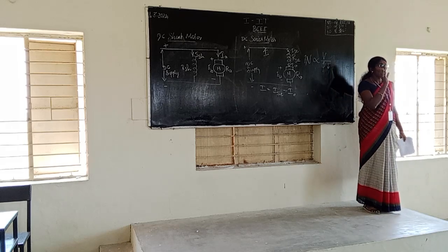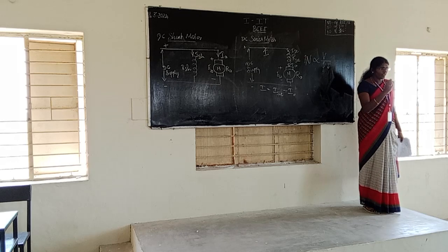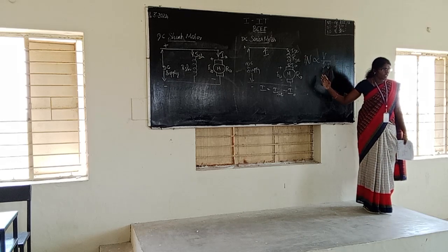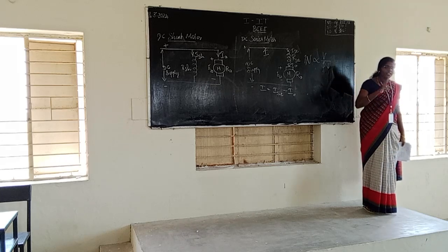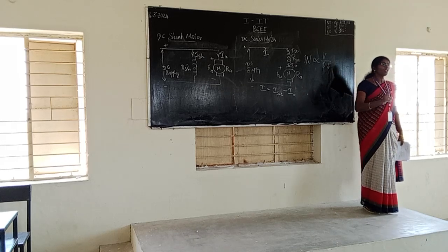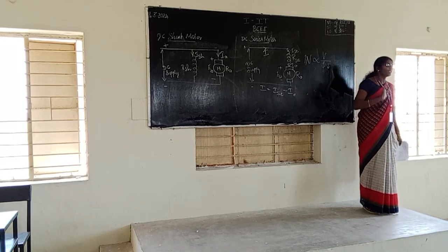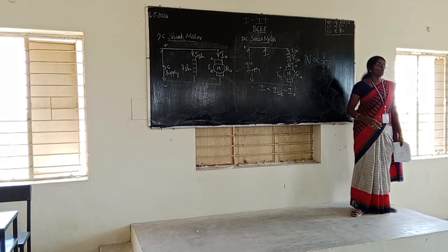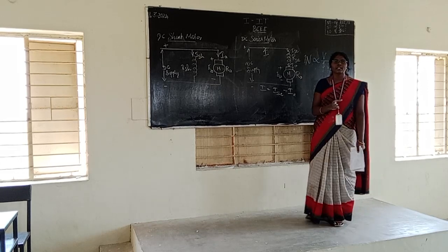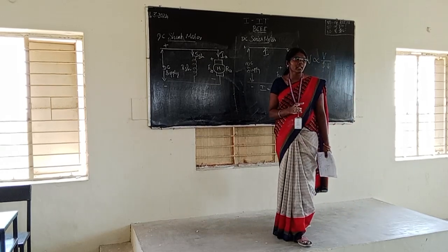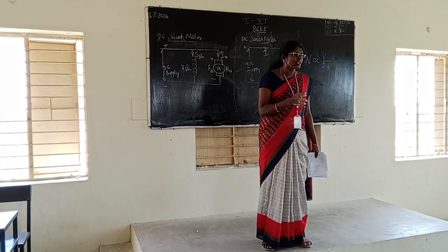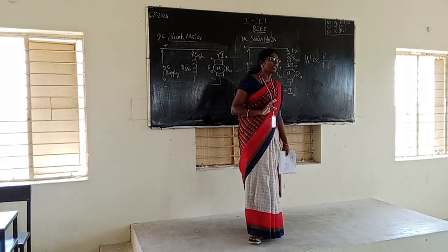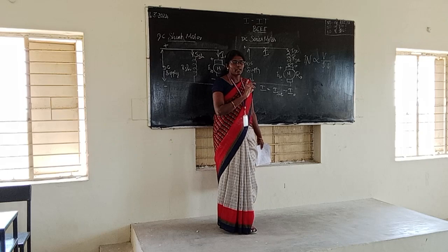What is happening at the no load condition? Flux phi is very small, or else we can say the current is very small, and the starting torque is very high, so that the speed is drastically increased. So we should not start a DC series motor at the no load condition. If we start a series motor at no load condition, the machine may get damaged, or else accidents may happen at the workplace. That is what you need to know of the series motor. Okay, and note it down.